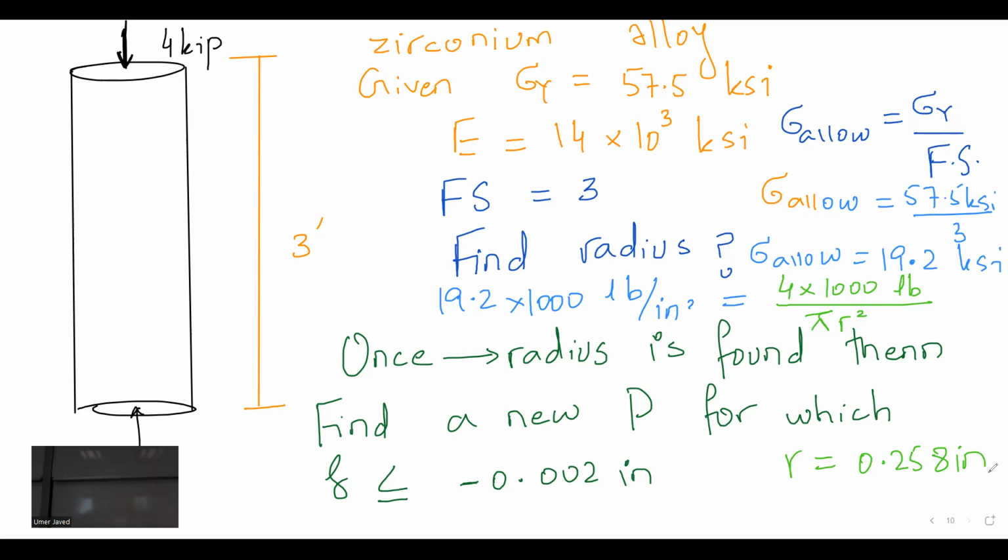So one way is that you say that elastic modulus is equal to stress over strain. This time your P is unknown, right? But there is another way, right? Do you remember that formula? PL over EA. I kept on saying. So do PL over EA and done.